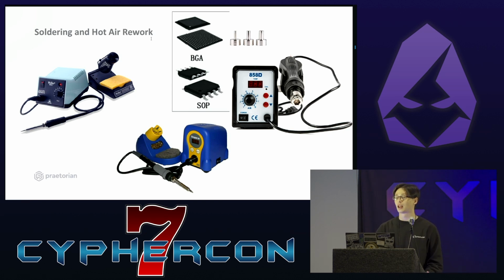But if you're looking to get a somewhat more serious upgrade, the big thing you're looking for is adjustable temperature control. So I have this light teal Weller WES51. I think they've discontinued it and replaced it with a WE2020, but that's a great option. The dark blue one at the bottom is the Hakko FX888, a very popular one that'll also serve you well for most applications. In the top right is a hot air rework station.